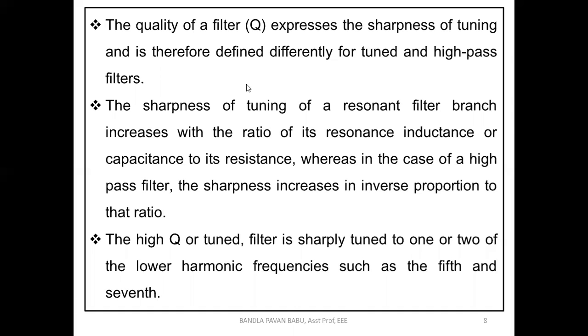What are the FACTS components? If you consider a STATCOM or SVC, SVG, or FC-TCR or TSC, likewise any of the components, all these are shunt connected. So we are going to inject the current. How can this current be controlled? This current is flowing through the filters, not the fundamental current. This is the harmonic current, which I can control with the help of the switches.